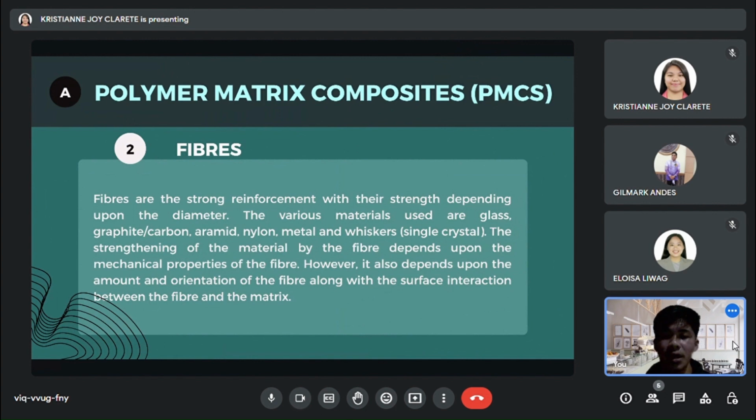So the fibers commonly found and used within PMCs include fiberglass, graphite, and aramid. Fiberglass has relatively low stiffness, at the same time exhibits a competitive tensile strength compared to the other fibers. The cost of fiberglass is also dramatically lower than the other fibers, which is why fiberglass is one of the most widely used fibers.